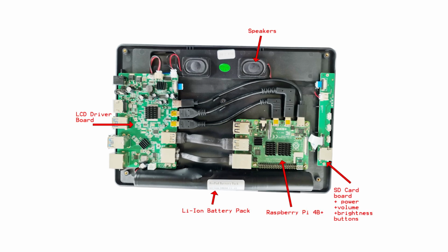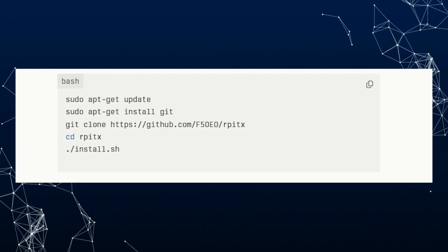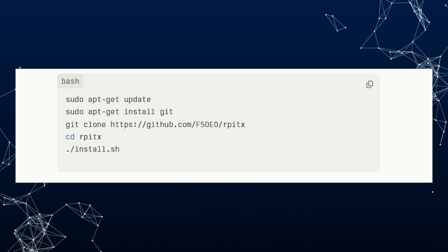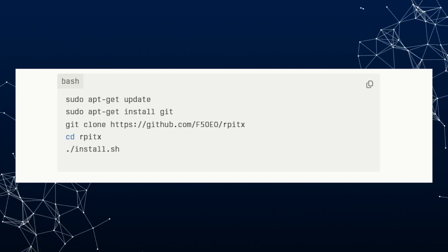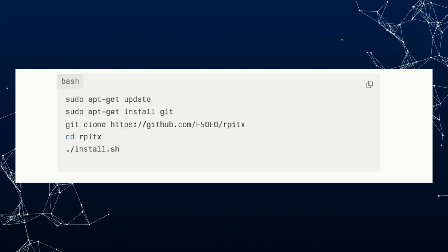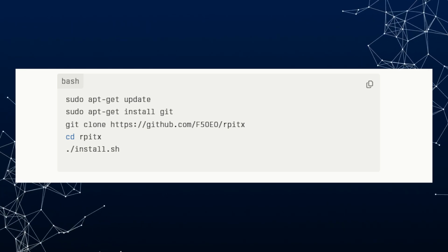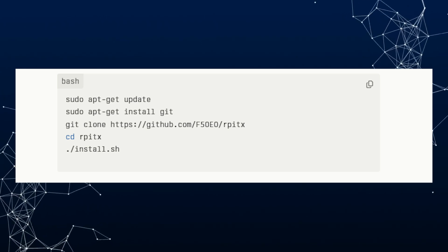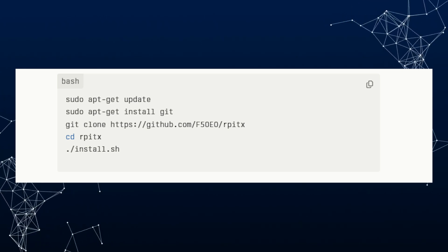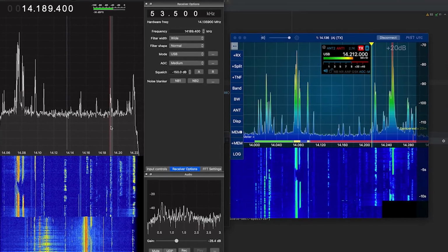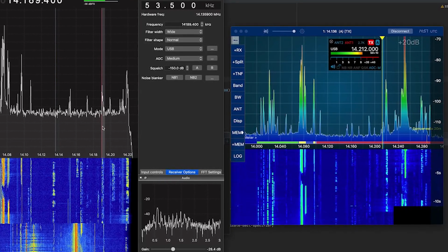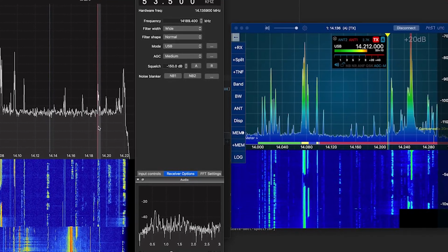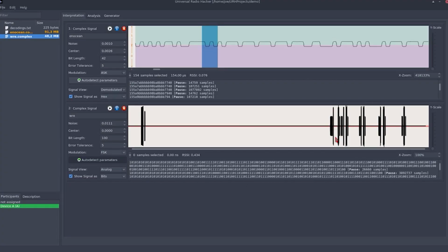Now the software installation goes as follows. Install the necessary software packages. Now Peter, please put that code on the screen. Install additional software like, again, we talked about it, but gotta say it again: SoapySDR, GNU Radio, and GQRX for signal analysis. Signal capture: use SDR software, like SDR Sharp, to identify the target frequency. Record the raw IQ data of this signal using the RTL-SDR.